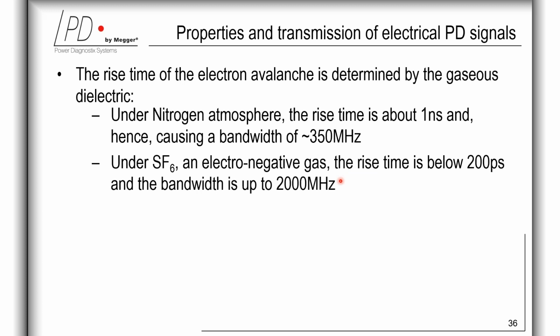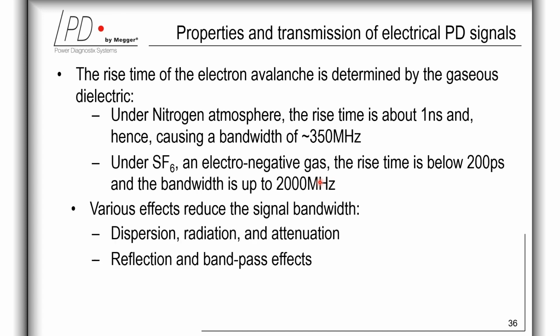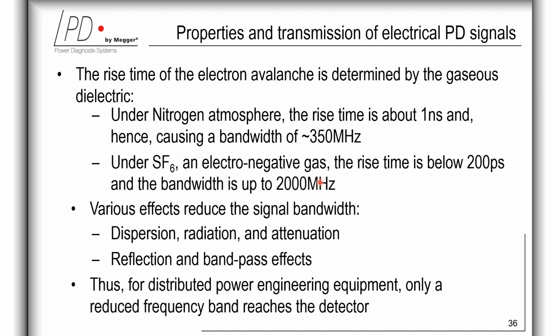However, whenever the test object becomes physically large, the influence of the internal and external leads has to be considered. This concerns effects such as attenuation, dispersion, and reflection. Likewise, the antenna effects, where we concern both radiation as well as the reception, including cross-coupling.